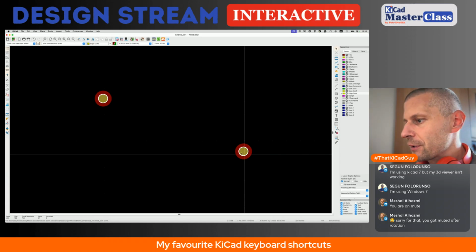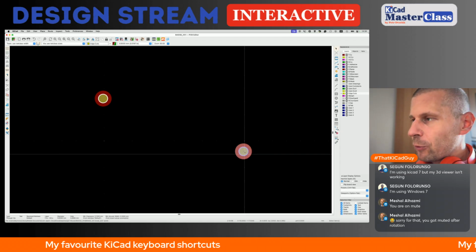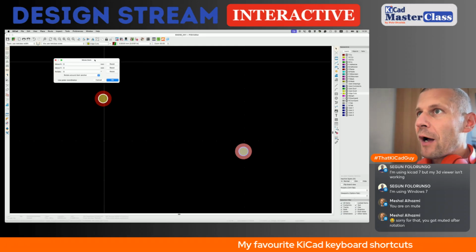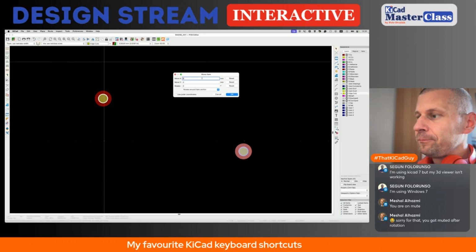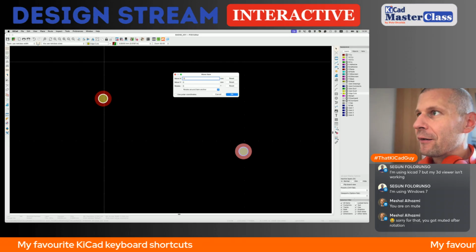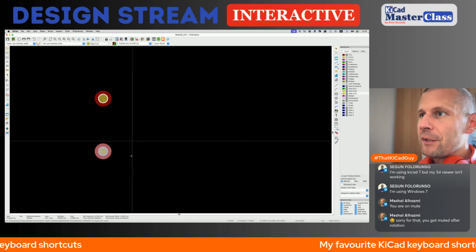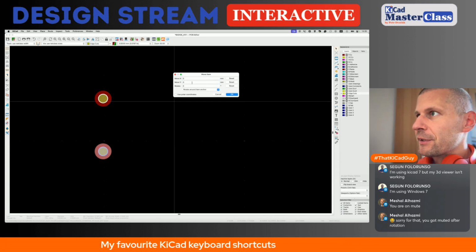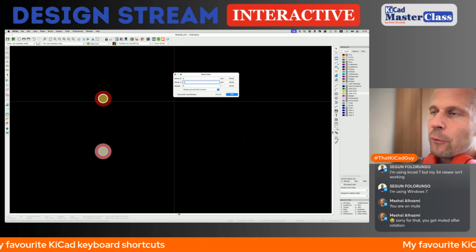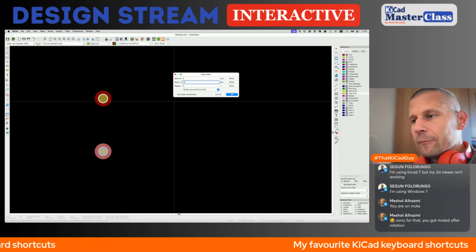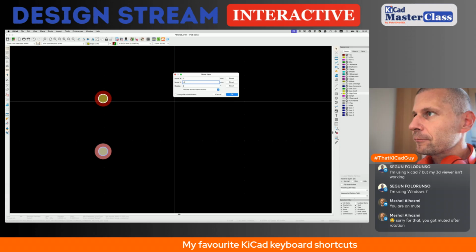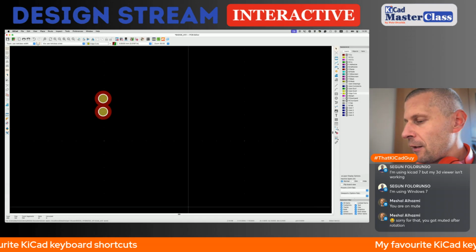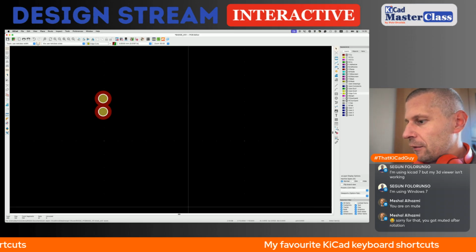So yeah, it works. When I want to move absolutely, it's not Shift P. Shift P is relatively. Shift M is absolutely. So move item, it moves like 5 millimeter back. -5 is here, and when I set now -2, these two vias would be stacked. I don't want to, so 1.5 and like this.